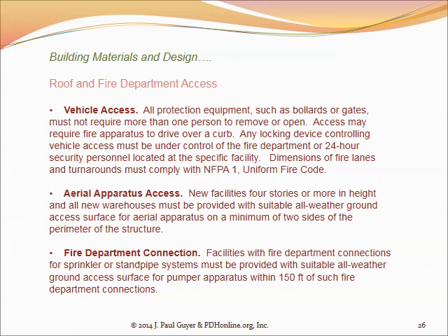And so the water is pumped into the vertical riser, rises up in the stairwell. At each floor, there is a connection where the firefighters, after they have climbed up the stairs, can connect their hoses, and that gives them a supply of water to fight the fire on that floor using their hoses. That's kind of the basic schematic there.